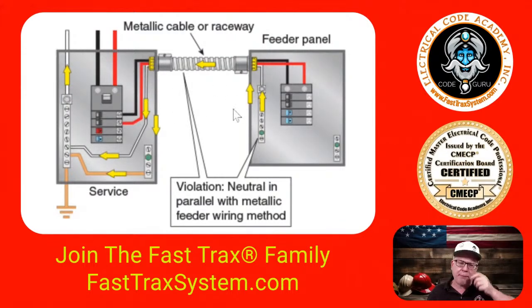Now, some people say, well, Paul, why don't we just use the raceway here? Or in this case, it says metal cable. That's all we need to do because 250.118 says that I can. Well, yes, 250.118 does give you a list of things that are allowed to be used as an equipment ground. But the conductors in here are probably larger than 20 amp protection, meaning the overcurrent device is larger than 20, because it looks like this is a feeder panel downstream.